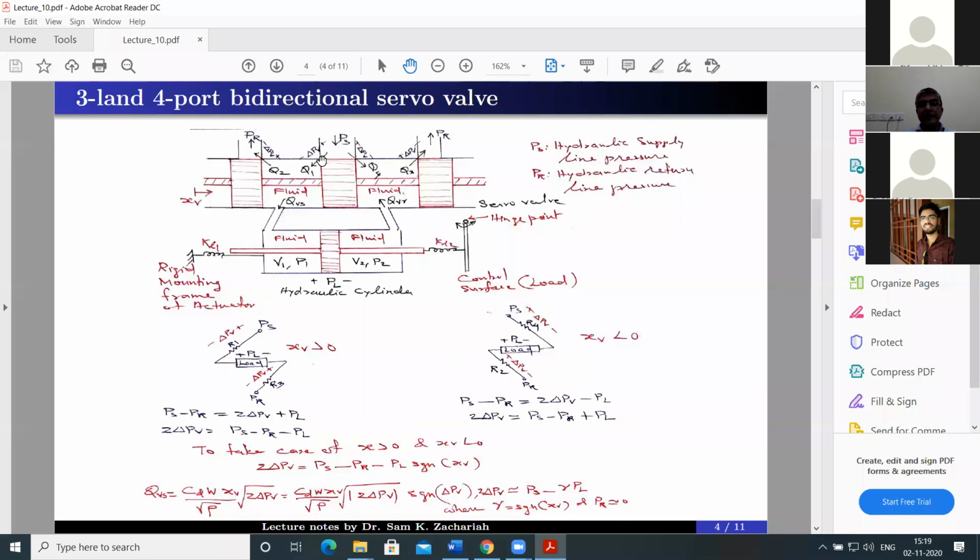Balancing comes when there is leakage flow. These two things are then not infinity. When they are not infinity, then simultaneously we have to consider all the resistances. But now I am considering the ideal case where in one case these two arms have infinite resistance, and in the other case these two arms have infinite resistance. So half of the Wheatstone's bridge is considered. If you are really interested to analyze more realistic cases, I am just coming to such cases where always all the ports will have some finite opening, then the actual Wheatstone's bridge arrangement will come. Okay.